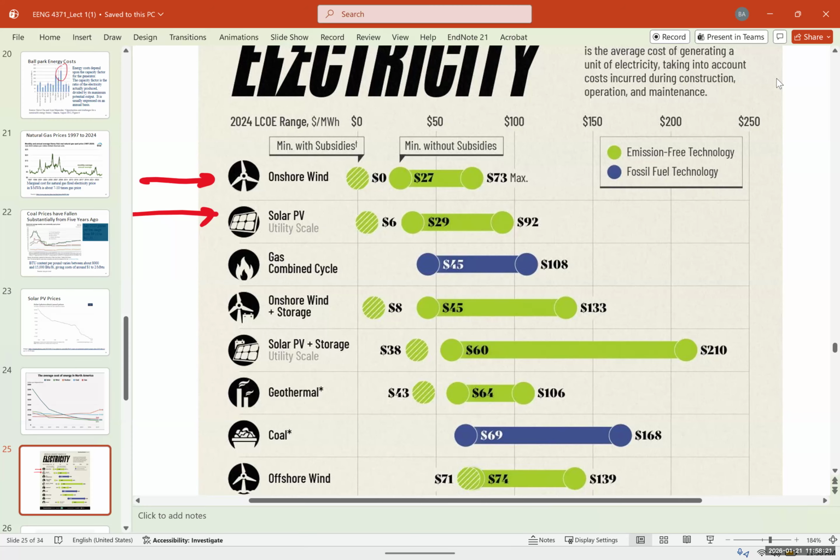It spins a jet turbine and produces electricity. Then the hot air from the exhaust goes into another system to heat up water, and that water is evaporated again, put through a turbine, and generates electricity. So it has a dual stage, what we call combined cycle natural gas. Those are the highest efficiency systems. These ones are a little older, and those have a price a little bit higher, between 45 and 108.